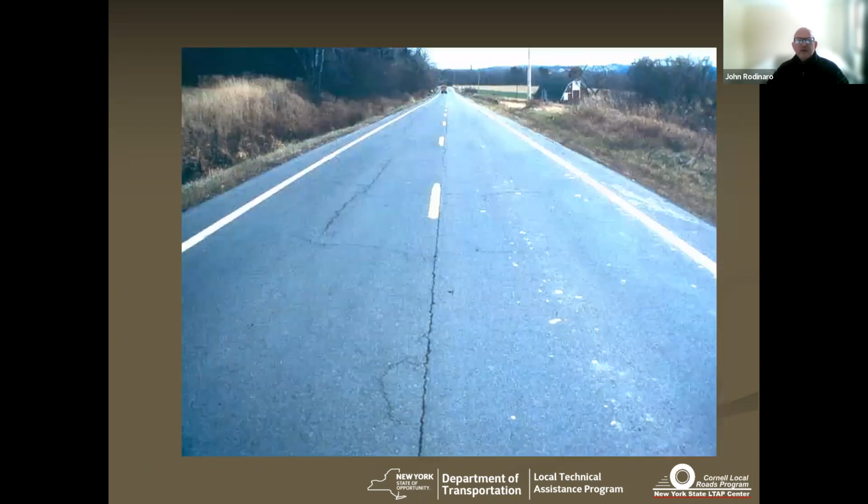This is a little further deteriorated. The edges are starting to get a little shaky. You're probably seeing a little bit of sloping to the bottom of the crack, from the edges to the bottom of the crack. It's getting right at the edge of being a good candidate, but still, because there's no interconnected secondary cracking, this is probably at the end of the window, but it's still a good candidate for crack repair.